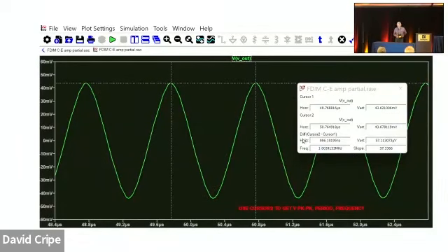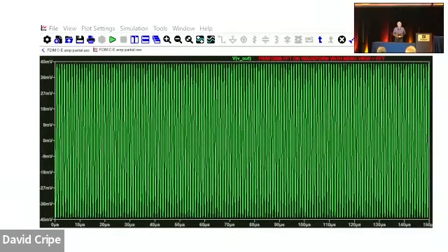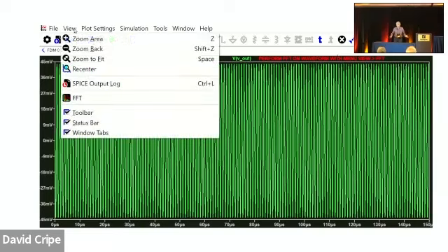Now I'm going between two crests. And again, at the bottom is the difference between the cursors. It's given me the period in time, and in frequency it says 996 kilohertz. That's pretty close because I started with a megahertz. I already knew it, but if this were an oscillator or a mixer or something, I might not know it.